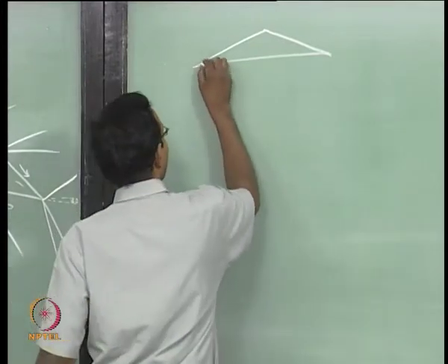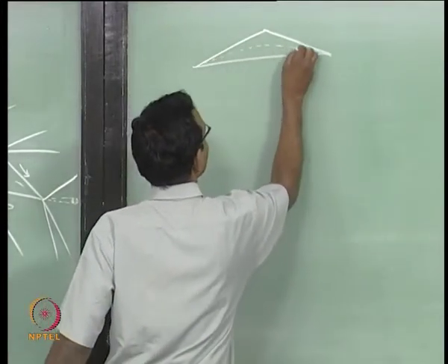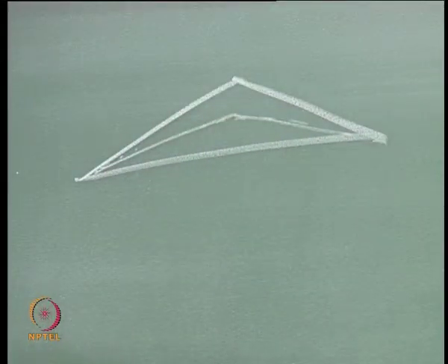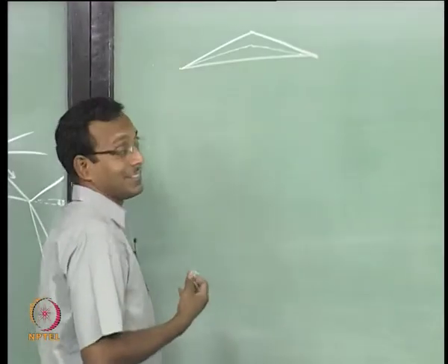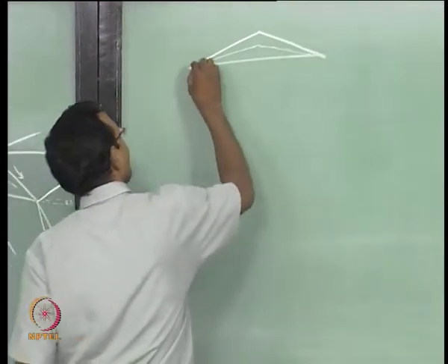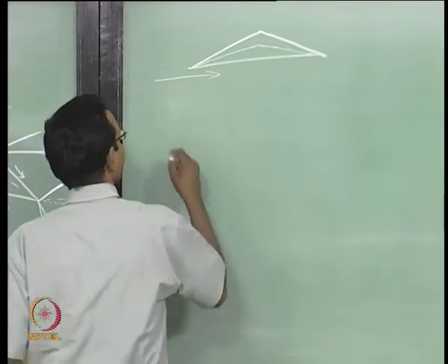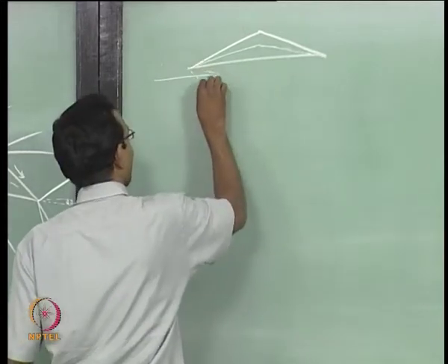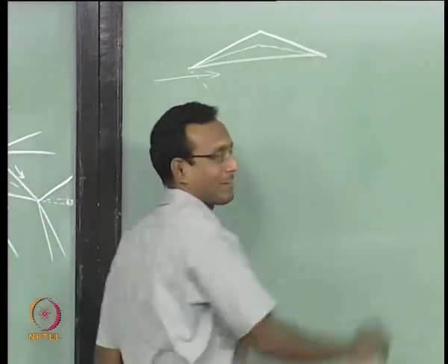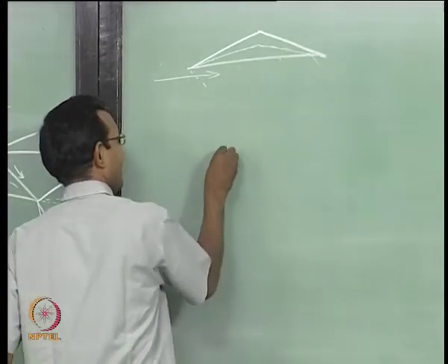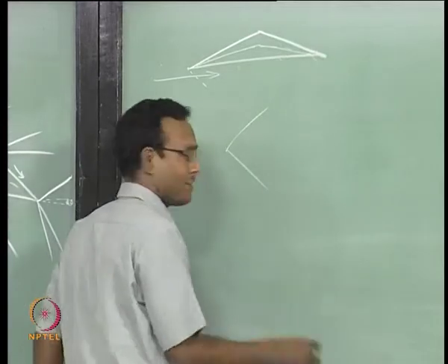If I think about the center line at every thickness, every cross section, the center line is going to go like this. In fact, it is going to go like a straight line to straight line. If I pick up some airfoil like this, it has to produce lift because it is a cambered airfoil. Will it? Let us see. I am going to say the flow here just goes straight. I am having 0 angle of attack. If at all there is any wave, it will be a Mach wave, and that will be everywhere. Remember that a Mach wave does not happen only at corners, it happens from every point in the flow. Even from somewhere here, there is a Mach wave going this way and this way. We are ignoring these Mach waves.